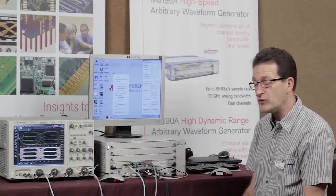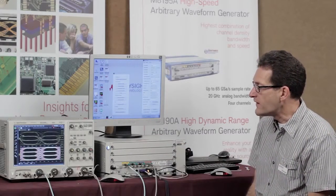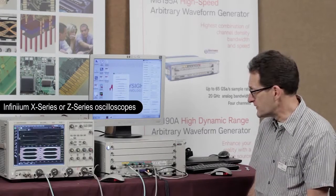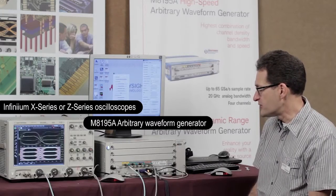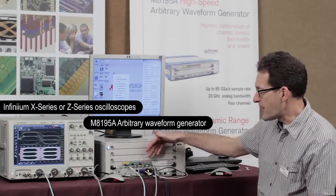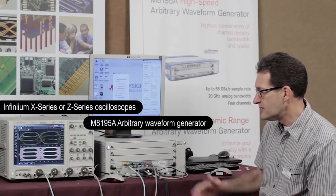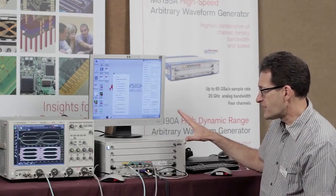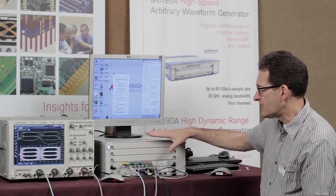Today I would like to show you how to use an arbitrary waveform generator in conjunction with our 33 GHz real-time scopes to generate PAM4 signals. I will be using our M8195 arbitrary waveform generator. This is a 4-channel instrument, so we can generate the PAM signal on any of those 4 channels or multiple signals together.